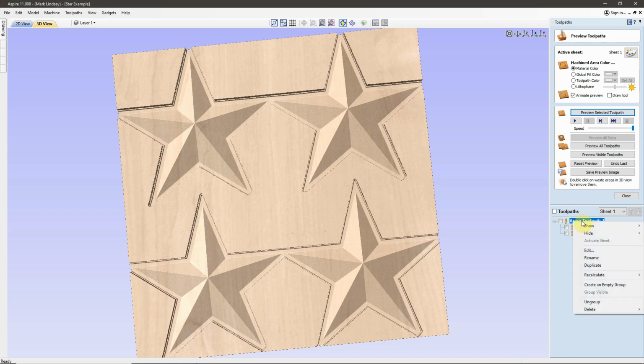You would right-click on that name, come down, and delete this. And that would send up a message asking you, did you want to keep the original toolpaths that make up this array copy? Well, that has changed. Now, if I come along and click delete this, it deletes everything.